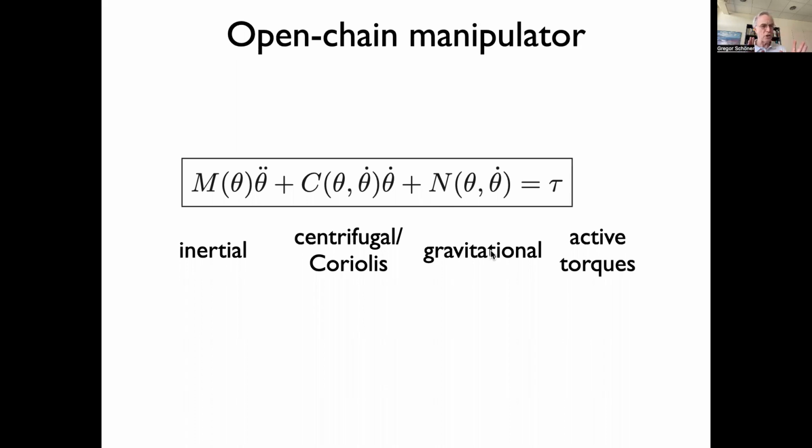So four-dimensional matrices that represent the general motion of a rigid body as a rotation and a potential translation. And with that, you can write as a product of such exponentials the general transformation from the base frame to the true frame and vice versa. And then you can write down the differential equation, the Lagrange function, in terms of those matrices.